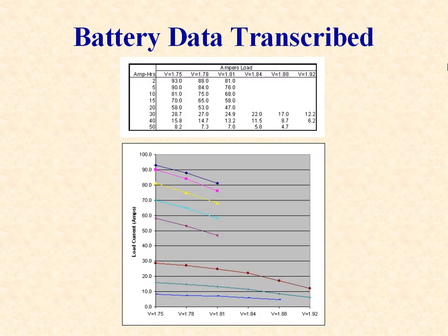Before we can enter the data into the library, it is usually necessary to carefully tabulate the data from the graphs. Unfortunately, the data is often less than ideal. Here we have shown some typical data transcribed from the available graphs. To get the best possible results from PTW, it is necessary to expand this data by supplementing the graphical data with information from the tabular form or by careful extrapolation.